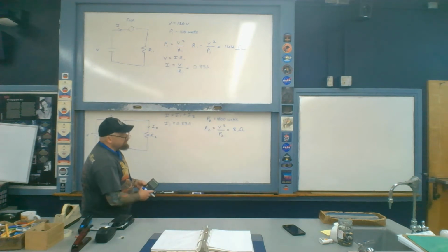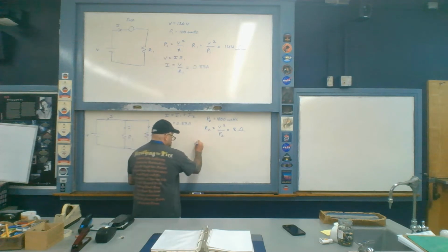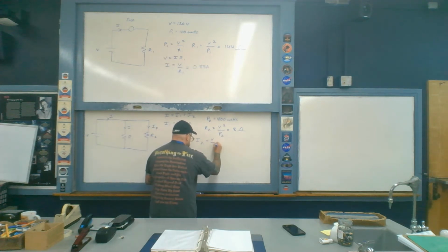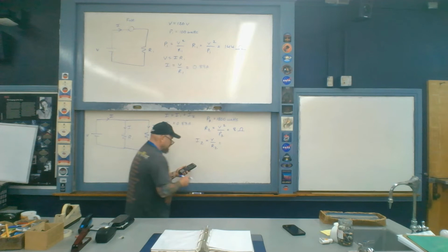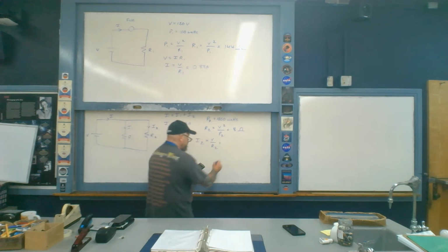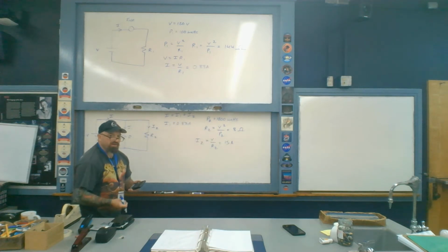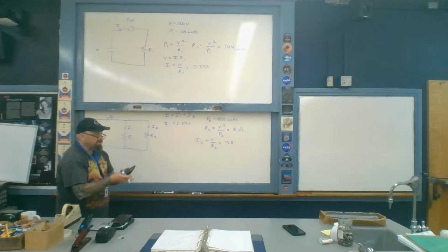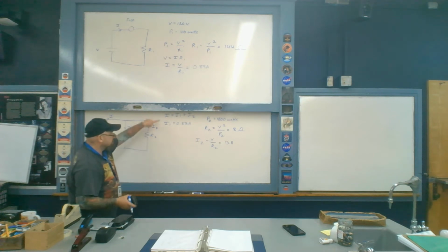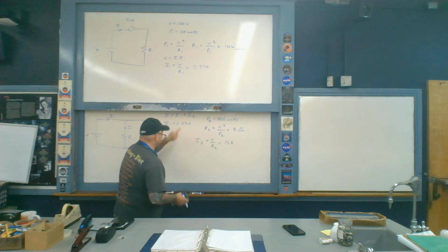So then therefore, using Ohm's law now, we can go ahead and calculate the current I2. So I2 is going to be the voltage V divided by R2, like so. So 120 divided by only 8 ohms, and this comes out to be 15 amps. So by turning on additional circuit elements in the parallel circuit, you then overall draw more current. Right now, the total amount of current I here is going to be 15.83 amps.